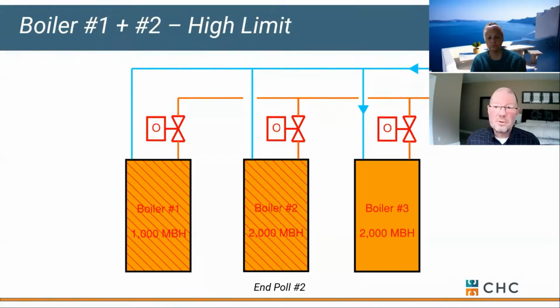I think overall it was 40 to 45 gallons a minute for 5 million BTUs. So yeah, flow is really lazy. As soon as you open up one of these motorized valves, it just wants to go there. It'd be way different if we had 300 to 400 gallons a minute rolling through a system. Okay, you could certainly, this boiler would create some resistance by itself and force it down here. But yeah, all depends on the system. Really valid point, good question. I hope I've answered that as best I can.